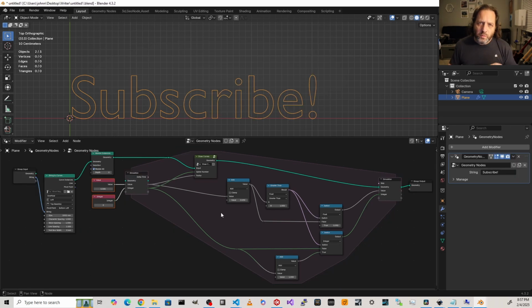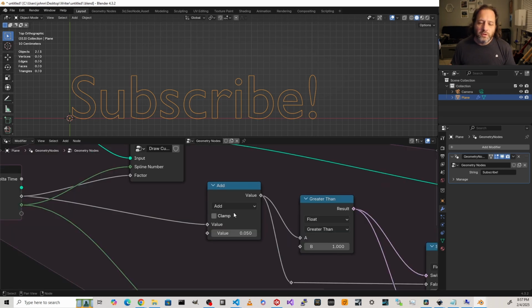Now let's say we want to adjust the speed that these are being drawn. Well, for each step through the simulation, we've been adding 0.05. That's kind of an arbitrary amount, so it's going to take 20 steps to go through each of the splines in this curve. Now, that speed is going to be affected by the frame rate of your animation.